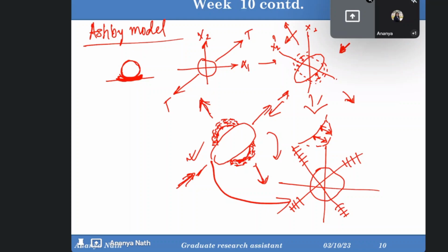Okay, ma'am. And if we are punching it out, we are making the same shape again, like we are just rotating back the shape. We are again in a spherical manner, making the load direction in such a way that the particle can have the original shape again, by distributing the dislocations or punching out the dislocations. So at the time of punching out, it will be well distributed in all four coordinates, all four axes of the elongated particle.